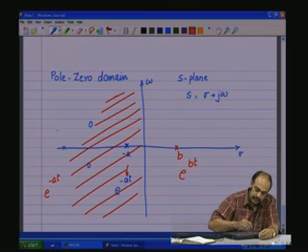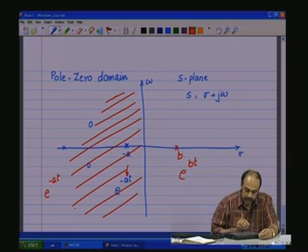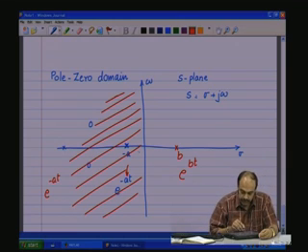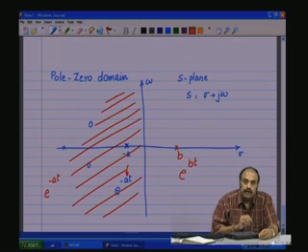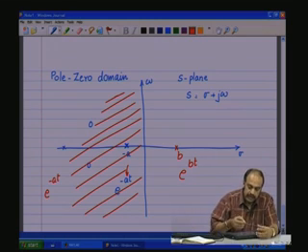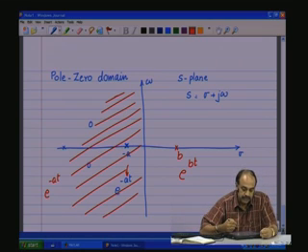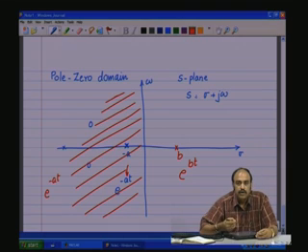So, all physical systems will have poles and zeros located on the left half of the S plane, and how close or far away from the omega axis or the y axis will determine the features and characteristics, the damping ratios, and the decaying nature, all those issues which can be used for synthesis of the circuit.